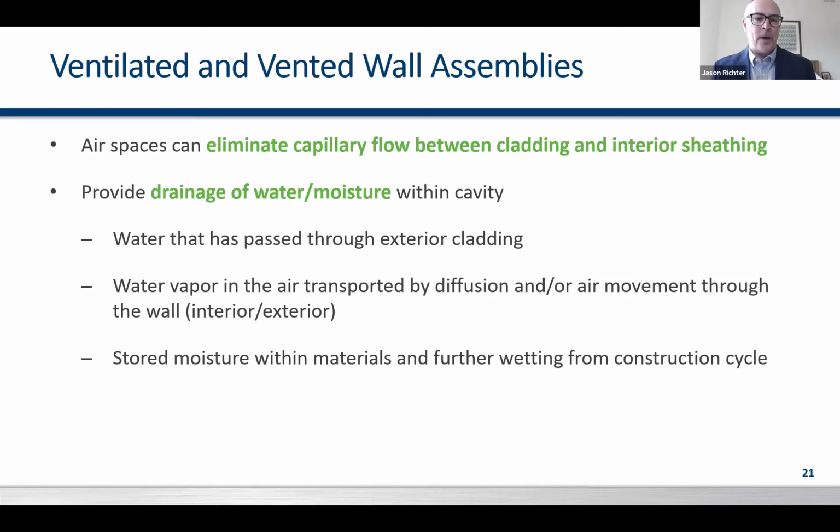A lot of panels do have an anti-siphoning capillary cavity to further reduce that from happening. That's mostly in what we call the exposed fastener world and not the concealed fastener side of things, which a lot of Rainscreens are these days on the concealed fastener side. So having that airspace in there is very important to the overall design of the Rainscreen assembly.